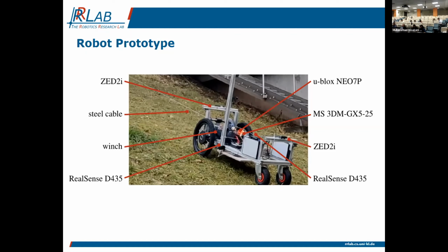We have here the differential drive, which we use to steer and propel the vehicle. So we are able to turn with different speeds of the different wheels, and can additionally propel the vehicle up and downwards. We have here also a GPS and an IMU which delivers the tilting of the vehicle, which we need because we have different tilting angles.